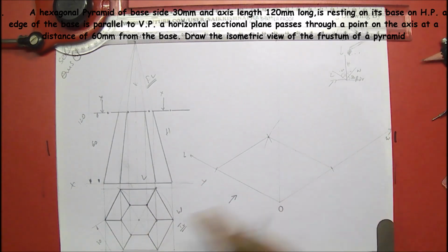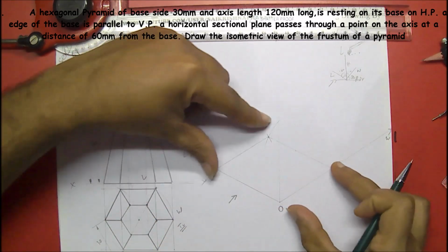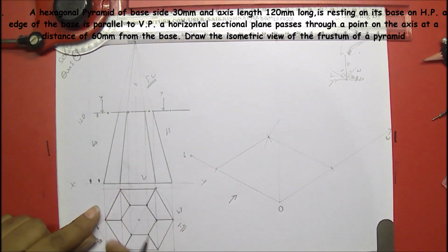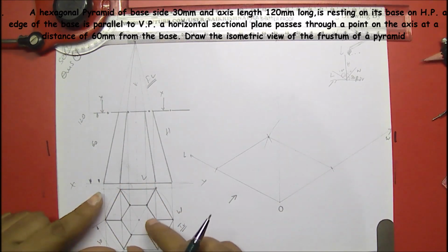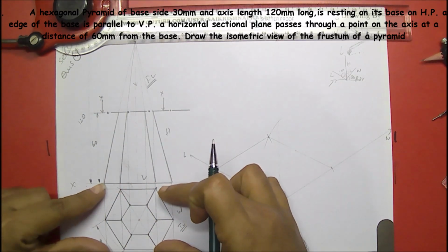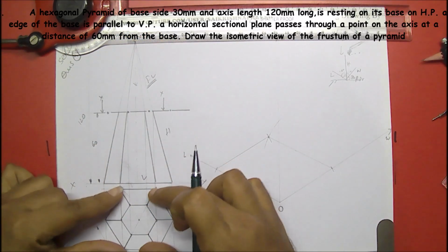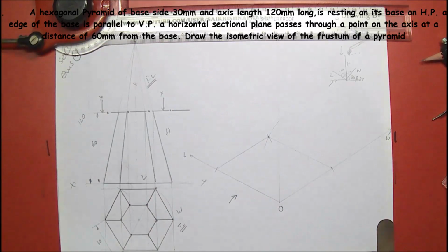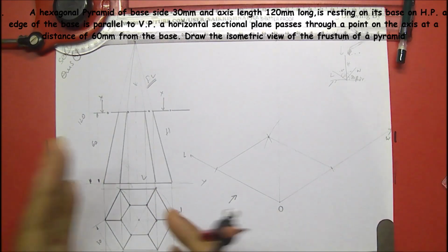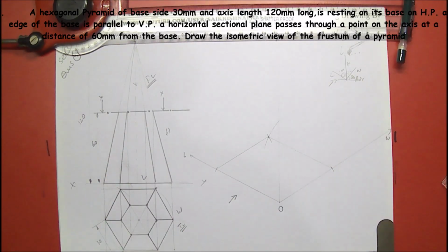Means simply you have drawn the box here. Means you have a structure of a hexagon in this box. Means you are reproducing the same box over here in isometric. So you can reproduce this hexagon also in this box. So this would become very easy when you are going from orthographic to isometric projections.